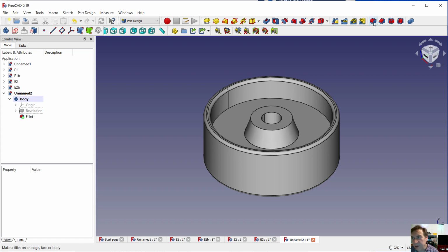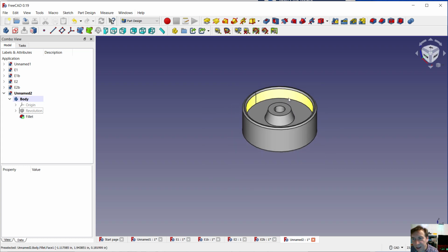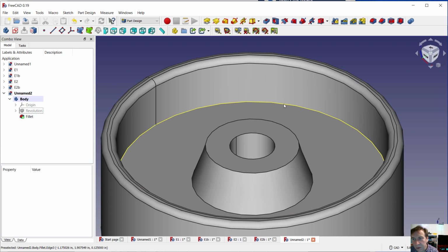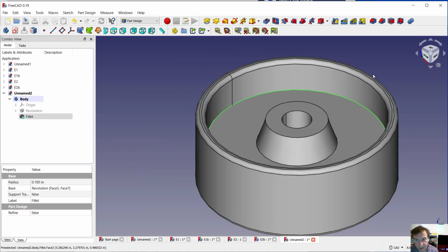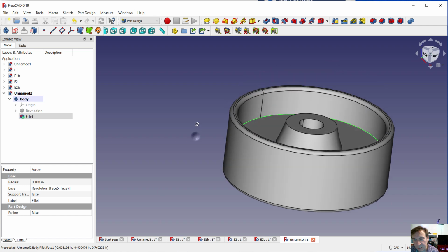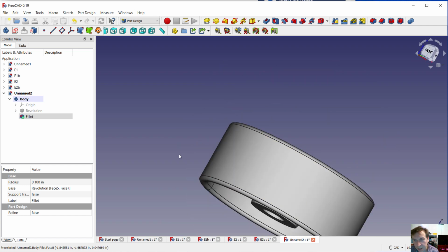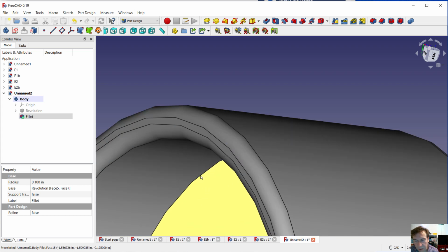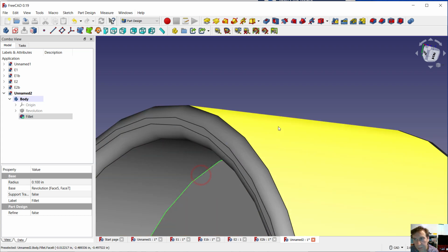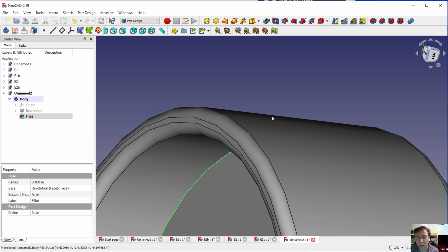But anyhow, let's go to select this edge. Now, selecting edges is not always that easy. Sometimes you have to move up really close and super precise. It's like playing darts here. Make sure the very tip of your pointer is on that edge. And then we'll roll it around, shift and the right mouse button. Oops. Get that edge. I've got to scroll up to it. There we go. Oh, and I forgot to hold control.